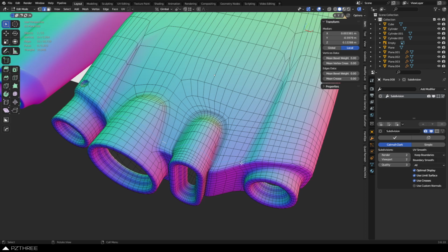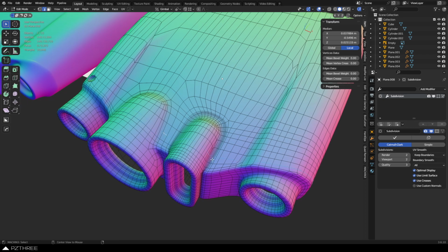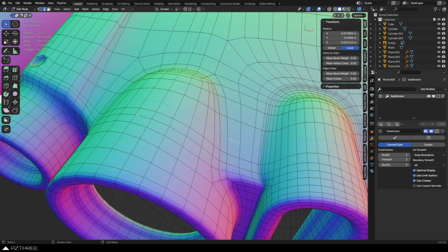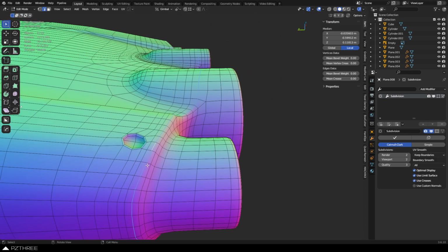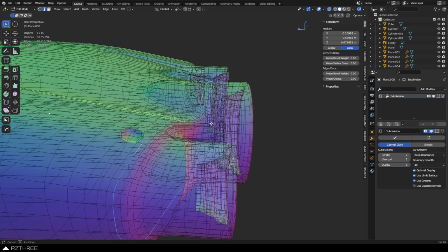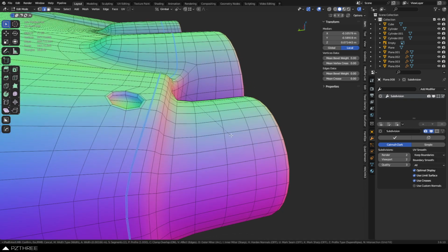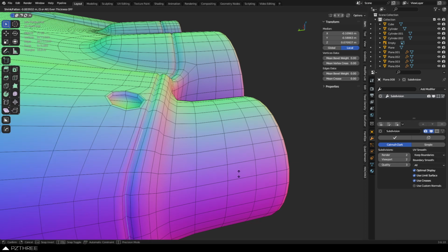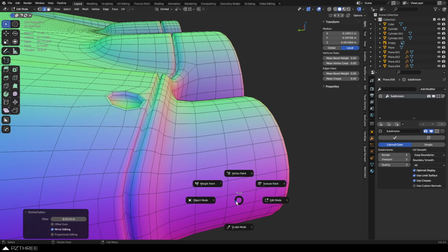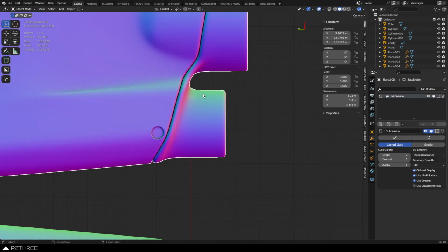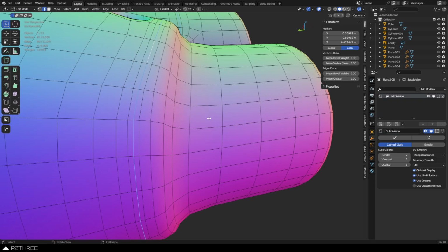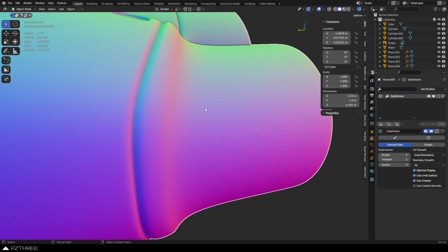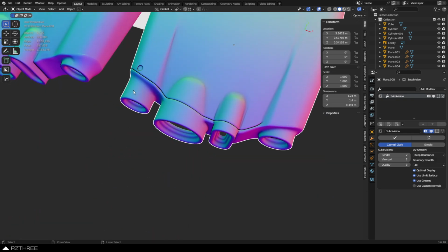And if you are doing just a quick bake mesh as well, just a side note here, I'm going to try doing it on this one maybe. I wanted to do it on this one. I don't know if that goes all the way around. Oh yeah, it does. Okay. If you're just doing a bake mesh and you're not going to split these apart into two separate pieces later, you could just do a loop cut and Alt-S that in quite a bit. And when it subdivides, you get that nice heavy bevel like that. Something you possibly could do, like a little crease or whatever the case there. Maybe push it in a little bit less. And you can see, very dramatic.